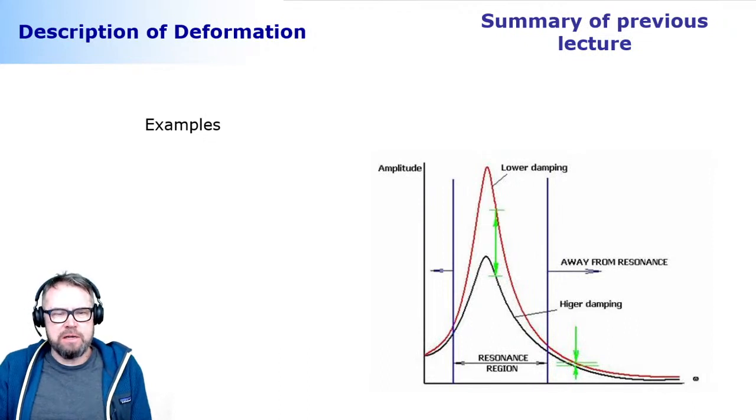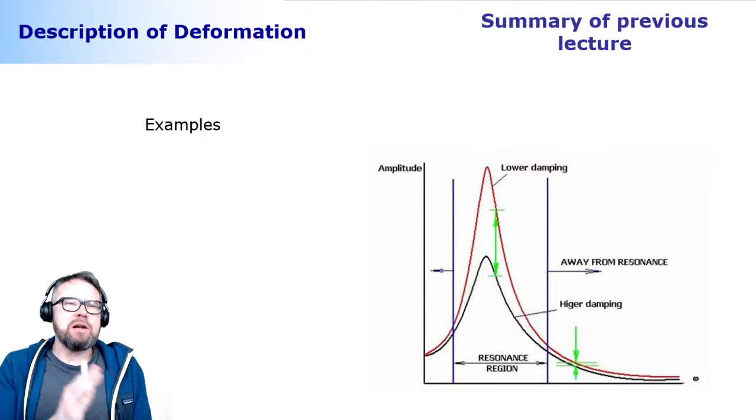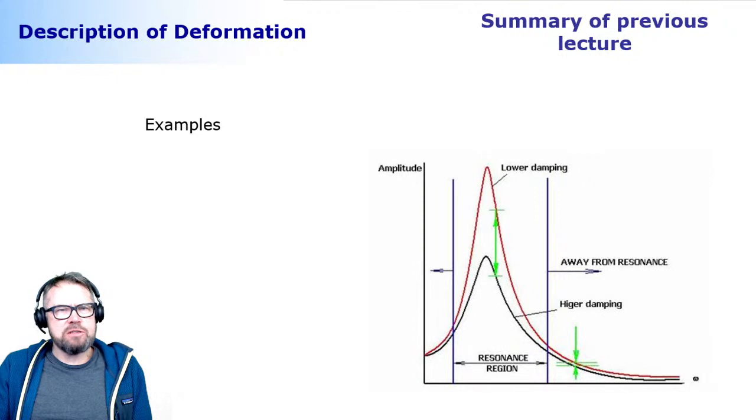Oh, what about the damping terms? This is really good. That's a really outstanding question. So what's going to happen to damping terms here? In most of the cases when conducting an eigenvalue analysis, particularly here in flexible multibody dynamics, we do not take the damping into account in eigenvalue analysis. It can be taken into account later, when we are damping the deformation modes themselves by introducing damping that is related to and affecting directly the modal coordinates. But in eigenvalue analysis, we don't take that into account. But that's a good question.